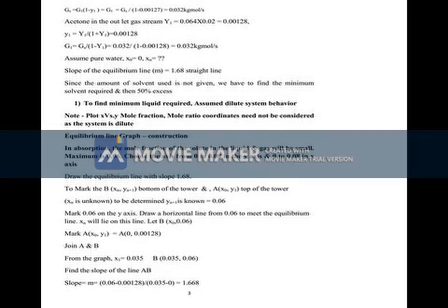After that we assume the tray spacing. Here what you will do is, in a packed column we find the height equivalent to a theoretical plate, but here we assume a spacing of 500 mm, and then we check for the pressure drop. So there are many design checks. One is pressure drop. What is pressure drop?